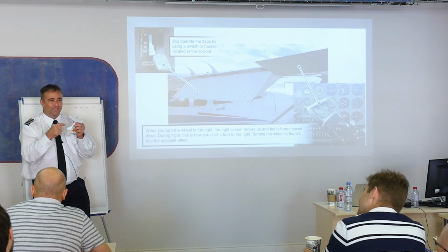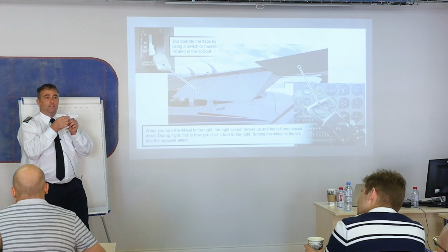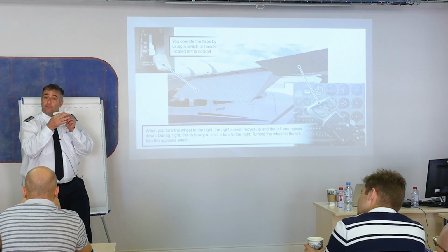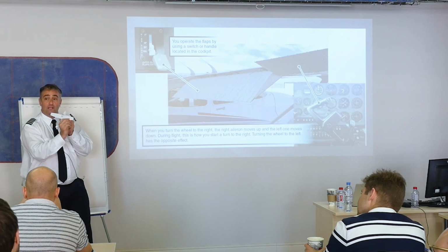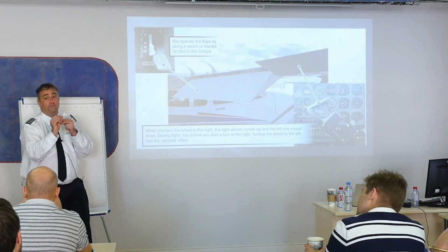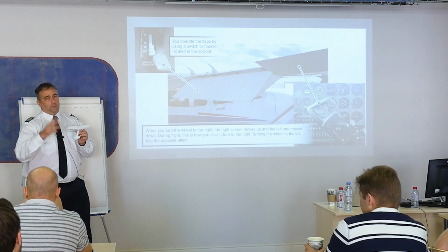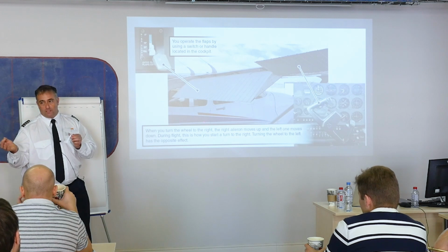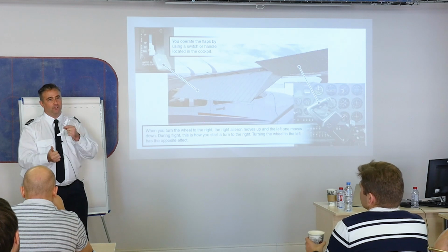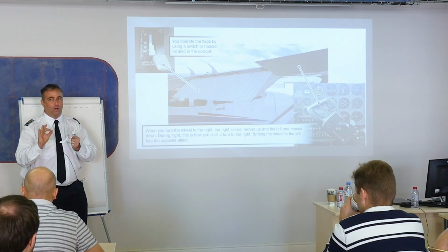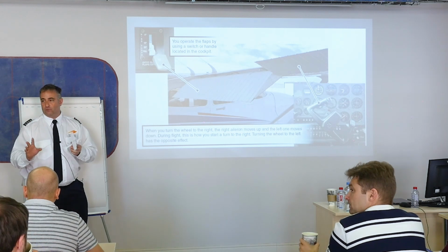It can stall here first, okay? So now what happens is I have maximum control of the airplane using my ailerons, even though I'm flying very, very slow and maybe very close to a stall. Well, that's bittersweet because if I do stall the airplane, I don't want to use the ailerons to control it at all, because then we could increase the likelihood that we enter a spin.